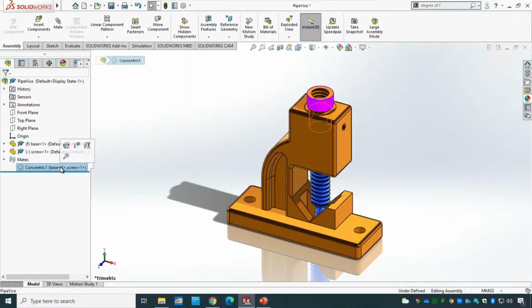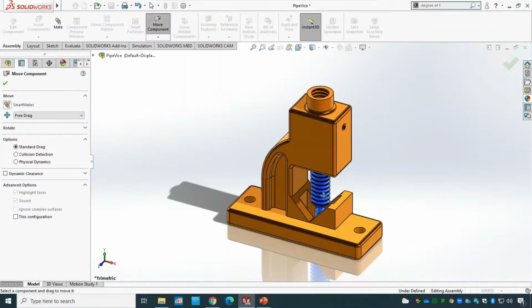And also if I click on there, it will try to highlight it for me as well. But as you can see here, the model went inside and I want to move it around. In case I want to move the part, I can go to the move component. I have to pick up the component that I want to move, with this one, and I will be able to move it as well, bring it up.